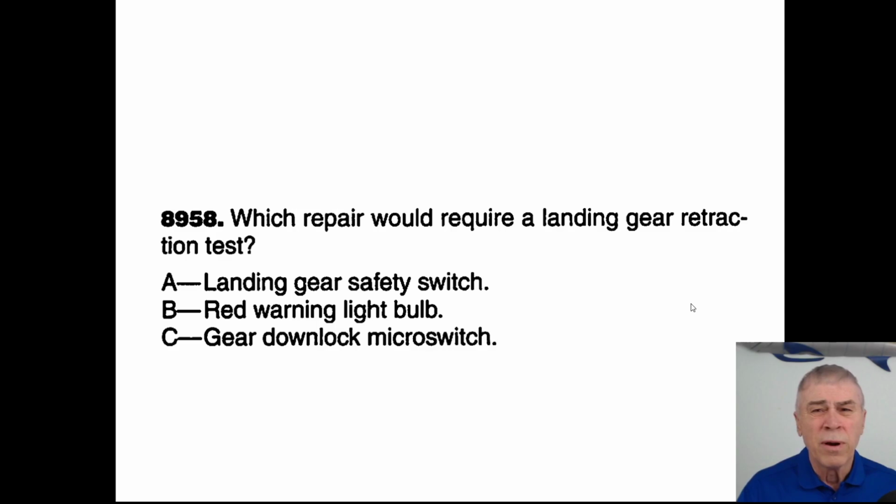So when would you require a landing gear retraction test? To make sure that everything is working. Probably if you change the actual micro switch, you're going to want to make sure that the micro switch operates and actually illuminates the correct bulb in the cockpit. So without doing too much overthought on the other two, certainly a light bulb wouldn't be it.